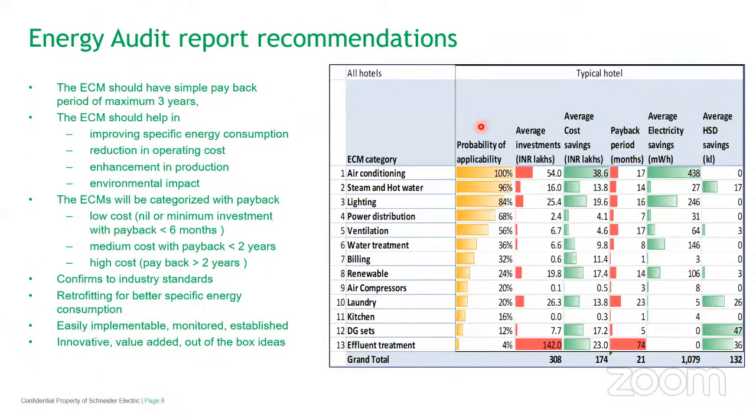Now I'll go to energy audit recommendations. After you do the measurement, how should you present this data to your end users, or customers, or wherever you are doing the audits? The first thing is that an energy conservation measure should have a simple payback period of typically a maximum of 3 years. Anything more than 3 years, most customers will not find attractive. They will not invest the money.